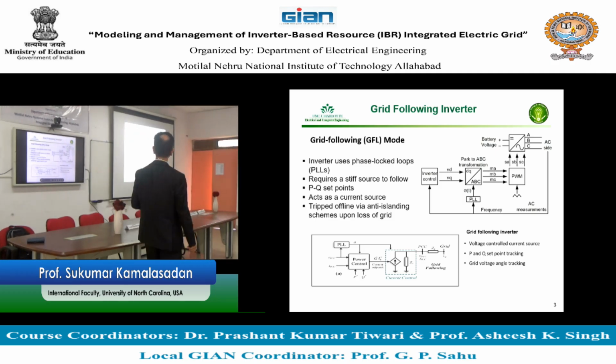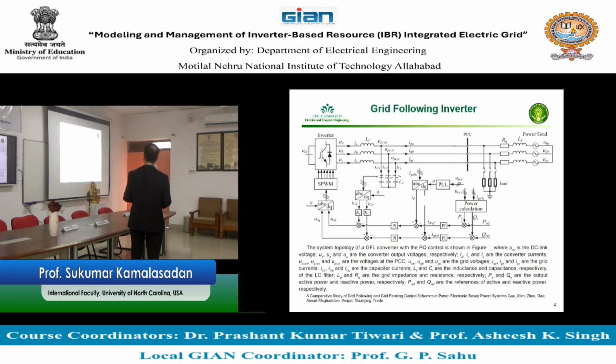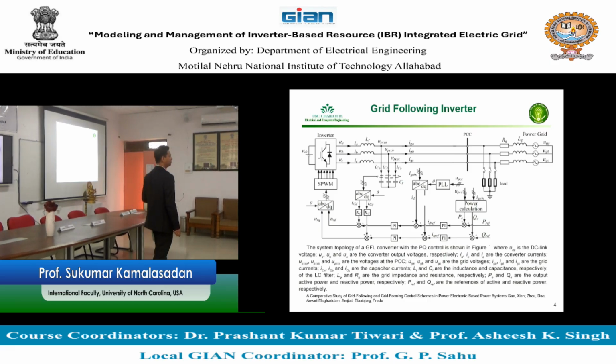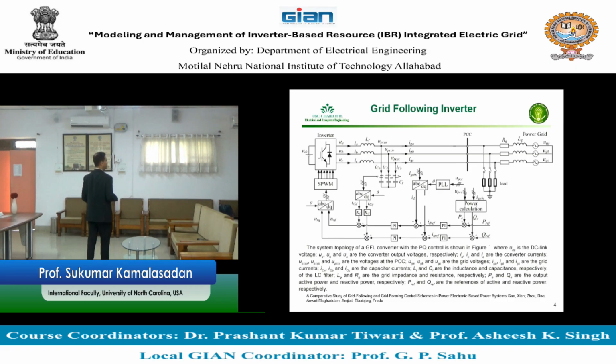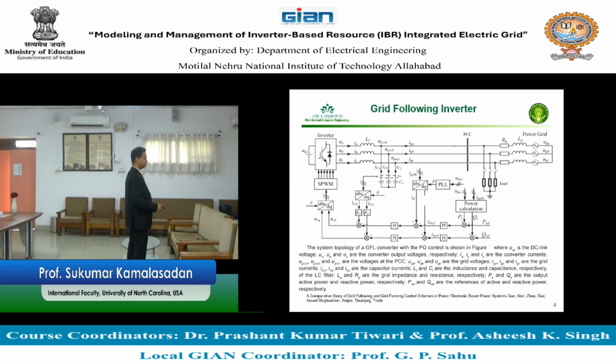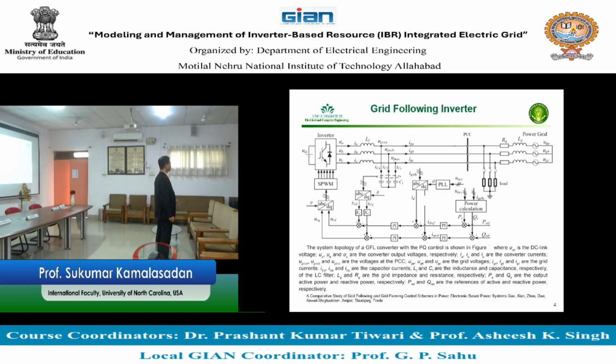So when you control an inverter, the inverter is basically what we call the front end of an inverter based resource. Okay, what do I mean by front end? Meaning the inverter is the one which connects the inverter based resource to the grid. Inverter based resource is not the inverter, right? It is actually the resource, and it could be, for example, a battery, a photovoltaic, or any other device that's connected behind the inverter.